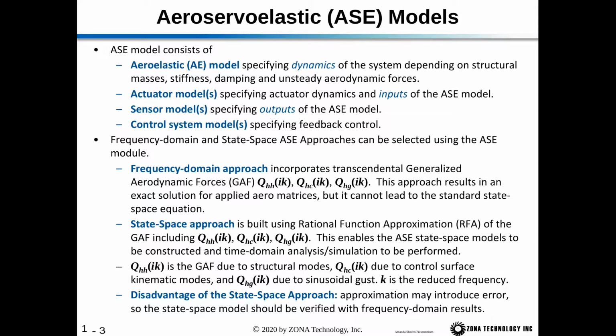This approach results in an exact solution for the applied aerodynamic matrices. However, it cannot lead to the standard state space equations. Next, the state space approach is built using the rational function approximation of those GAFs. This enables the ASE state space models to be constructed and the time domain analysis and simulation to be performed.